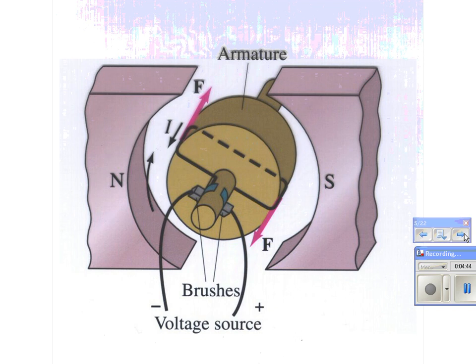Okay, you take a coil of wire. You place it in a magnetic field. You have a device here so that as my coil of wire rotates, it rotates this axle, which has the connections on it that are connected here and here to my electrical source. Notice this is the positive terminal, this is the negative terminal. These things, which are called brushes, don't move.